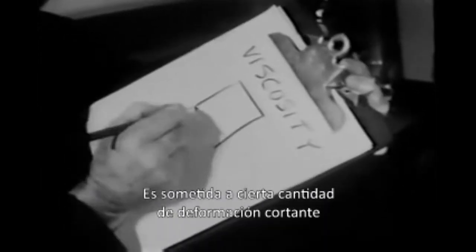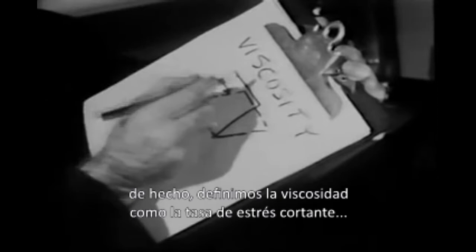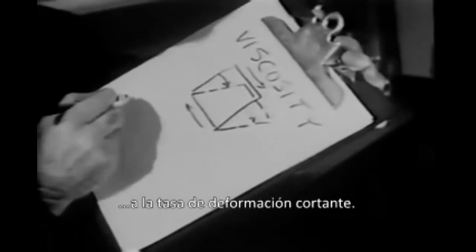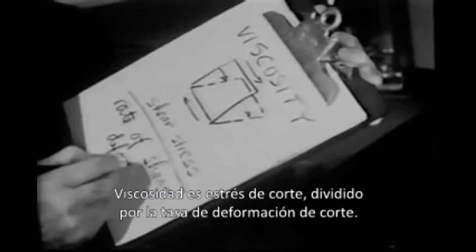To be more precise about viscosity, suppose that an initially square piece of fluid undergoes a certain amount of shear deformation, as measured by this angle. Then the viscous resistance appears in the form of tangential or shear stresses required to produce this shear deformation at a certain rate. In fact, we define the viscosity as the ratio of the shear stress to the rate of shear deformation. Viscosity is shear stress divided by rate of shear deformation.